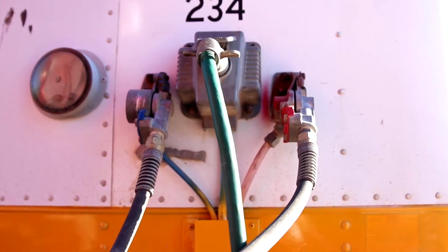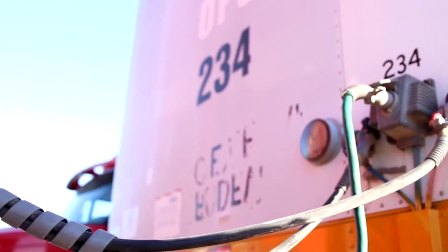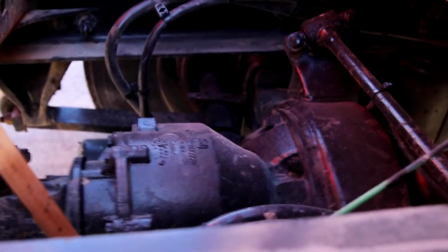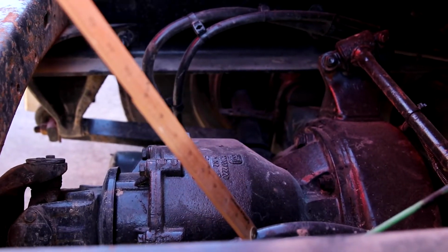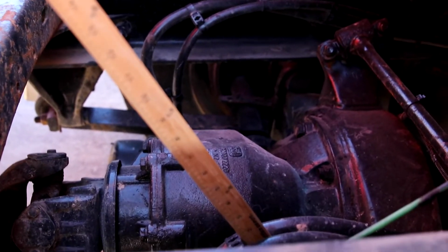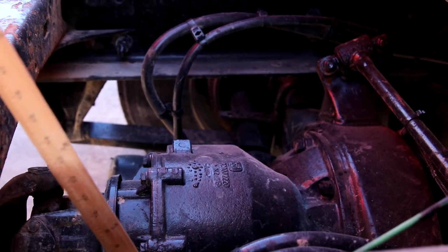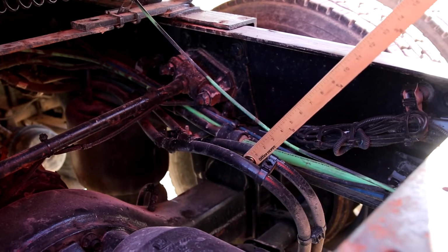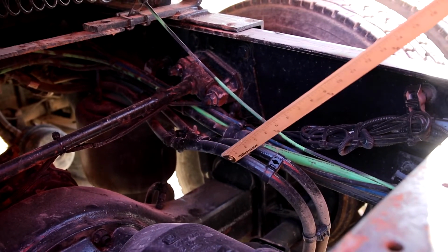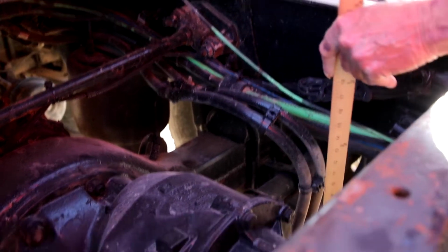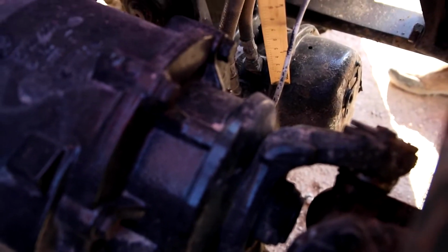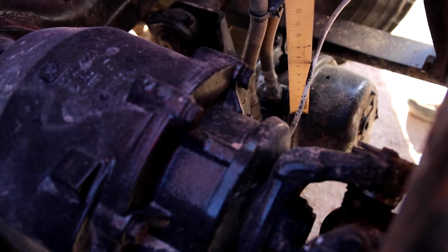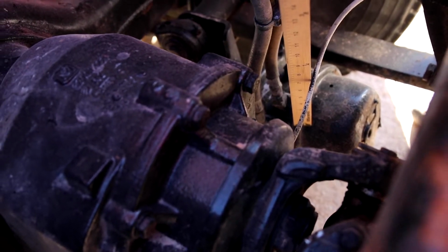Then we get to step inside and do the brakes again. My air lines leading to my brake chamber are mounted securely to the vehicle. No abrasion, bulges, and cuts. No audible leaks. This truck also has an ABS system. All right, our air lines are securely mounted to the vehicle. There's no abrasion, bulges, and cuts, and no audible leaks, leading down to the brake chamber here. My brake chamber is mounted securely to the vehicle. It's not missing, damaged, or broken. And again, it has no audible leaks.